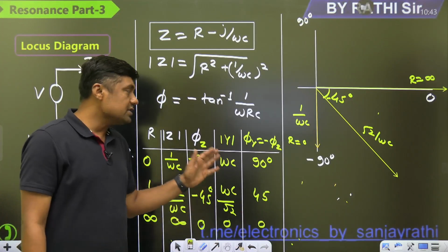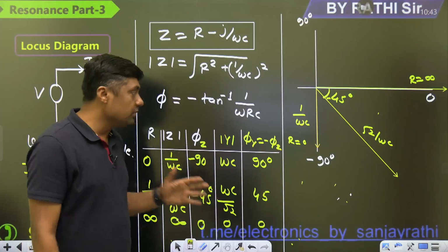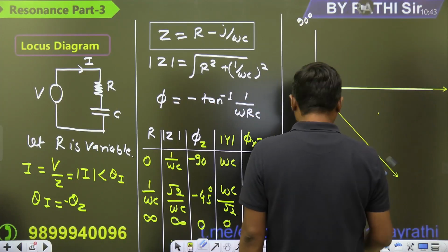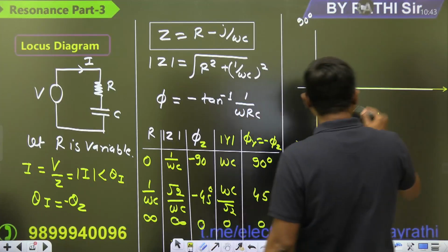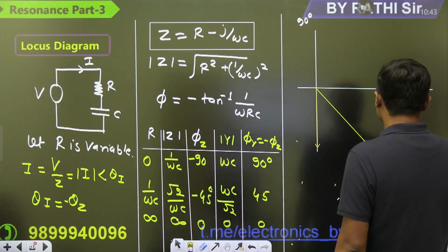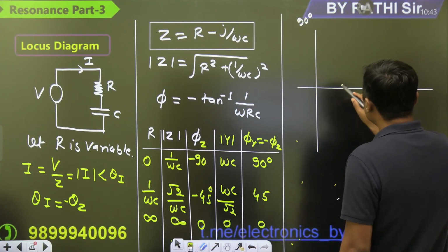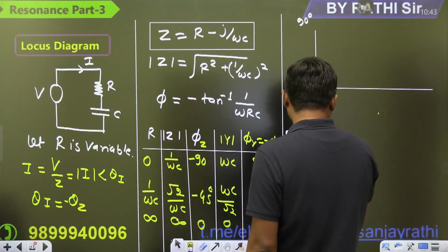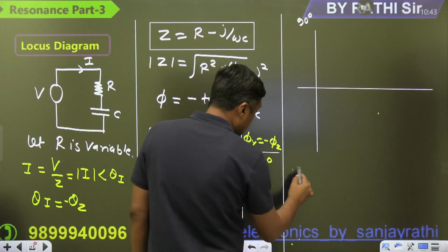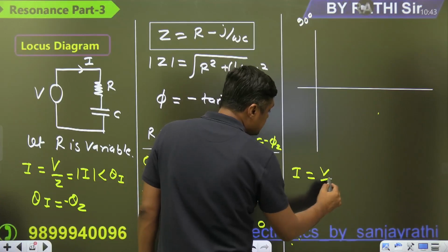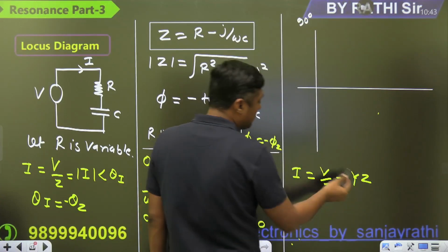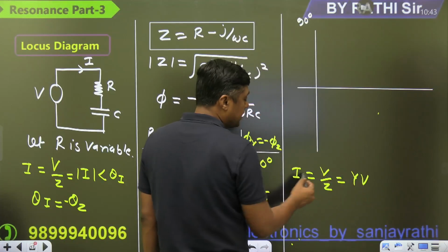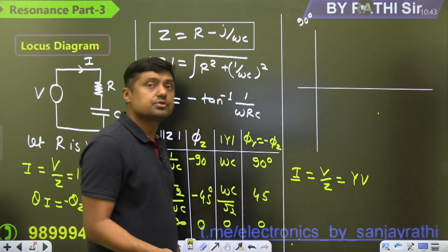So we are getting the phasor for what? Y, just like I. Same, similar. And that's why a number of numericals give I. You have to plot the phasor for I or the phasor for admittance. Both are similar type. Why similar type? Because current is equal to V by Z, or what? YV. It is directly proportional to admittance Y. And if the V is constant, so the I phasor and V phasor are almost similar.